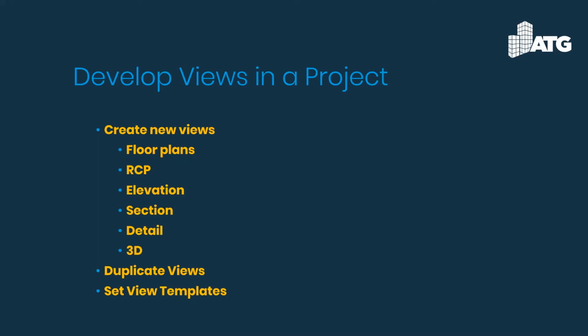It's telling you that when I delete levels 4, 5, 6, 7, and 8 out of the project, it's going to remove all these floor plans, all these reflected ceiling plans, anything that's associated to levels 4 through 8. So it's cleaning that up for me when I delete out those levels.